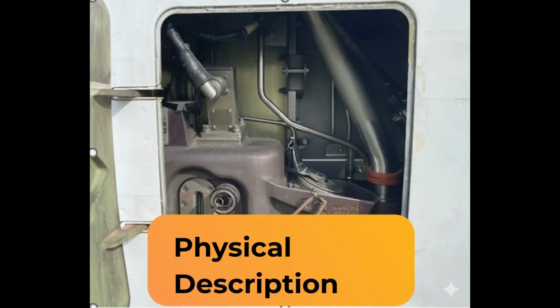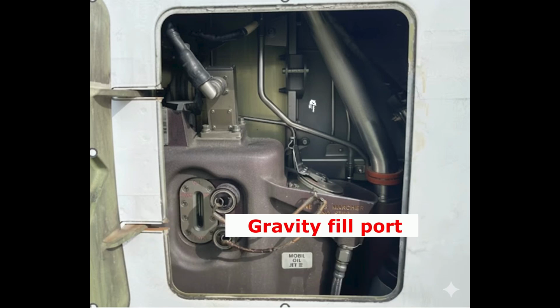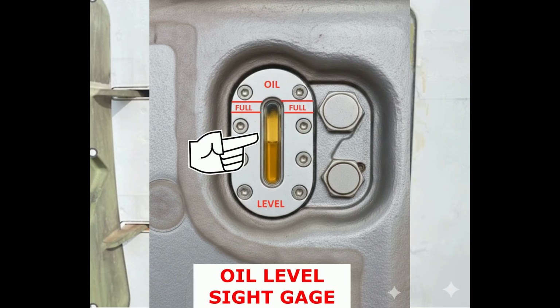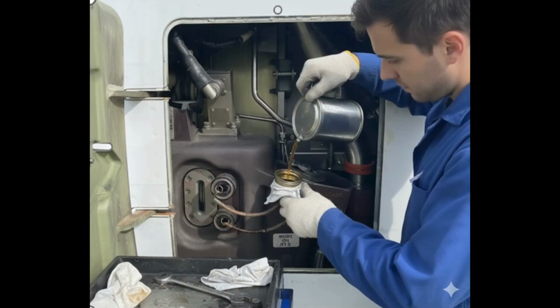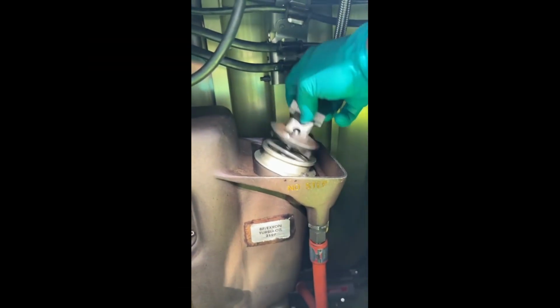Physical description. The oil tank is equipped with an oil level sight gauge, a gravity fill port, and a pressure fill port. Oil level sight gauge. Positioned on the forward side of the oil tank, the sight gauge is used for visual inspection of the engine oil quantity. Gravity fill port. Located on the upper right side of the oil tank, this port is used for manual filling. The filler cap features a locking handle. The technician releases the handle to manually fill the tank.